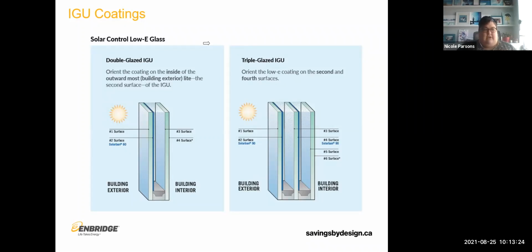That's not something that would typically stay that way. And if only a couple pieces of glass are put in backwards, you can visibly see the difference from the outside. So that's something that typically gets addressed, and it ends up not being something you have to reflect in your energy modeling. Things like incomplete seals around the perimeters, increasing air leakage, those are things that we are still struggling with as an industry in terms of reflecting that in energy modeling.